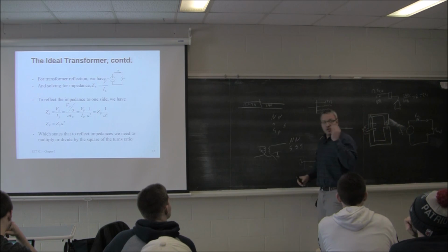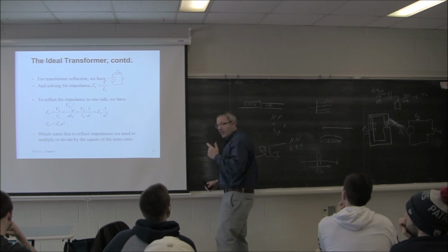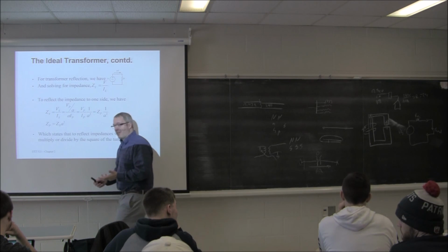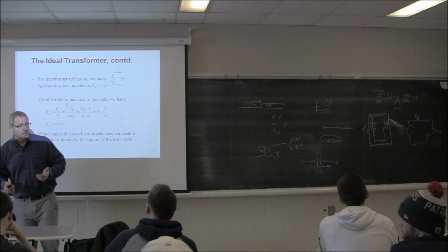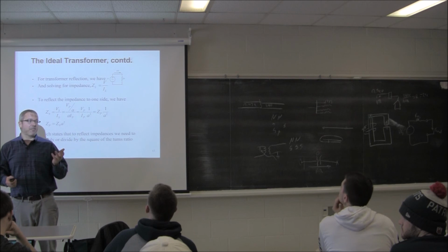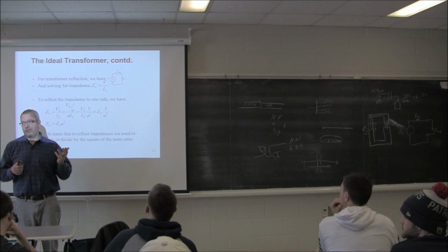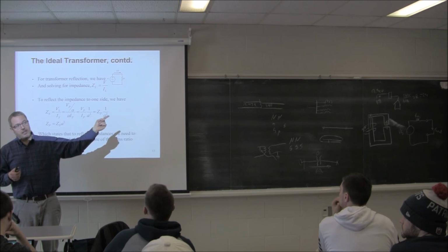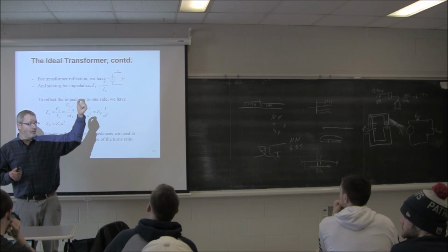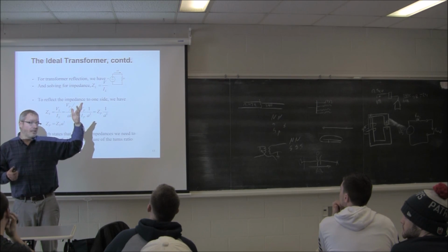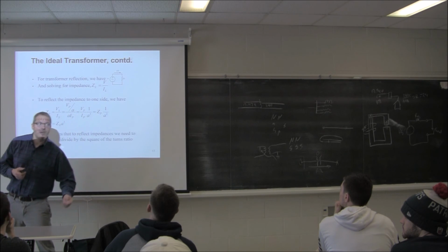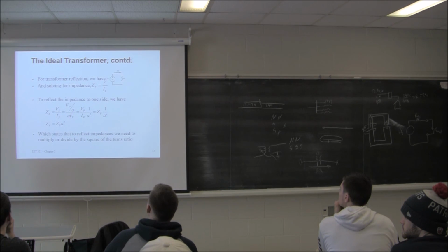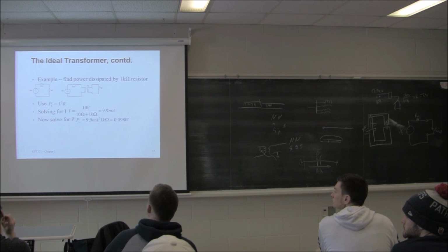And most of the fuses that you see on a distribution circuit, the reason why we use fuses is because a breaker can't detect those, because going to your house, you might look like half an amp, if that. If you're going down the street and you look at a distribution circuit that's peeling off the main street, you'll usually see a fuse cutout. That fuse might be 3, sometimes 5 amps, and that's all you need to run to an entire neighborhood. Okay? That's how we do the turns ratio.